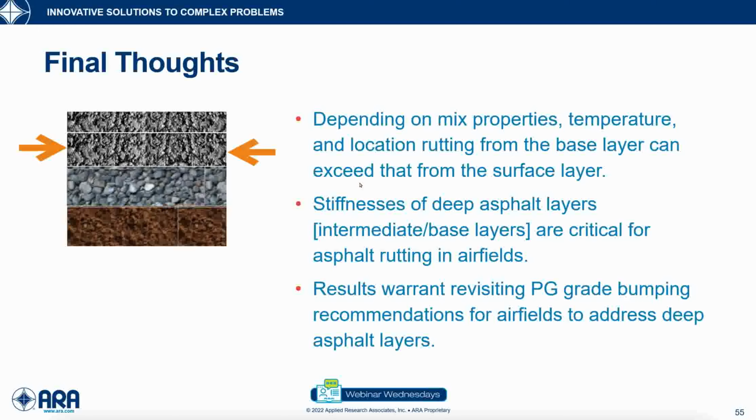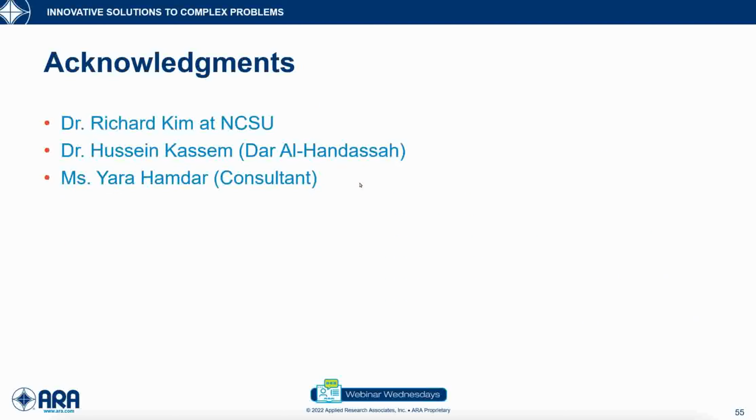And the results do warrant revisiting the PG grade bumping recommendations for airfields to address deep asphalt layers. So maybe we need to emphasize that deep asphalt layers do require PG grade bumping. We need to stiffen up the binder. We need to stiffen up the mixes of base layers in airfield pavements.